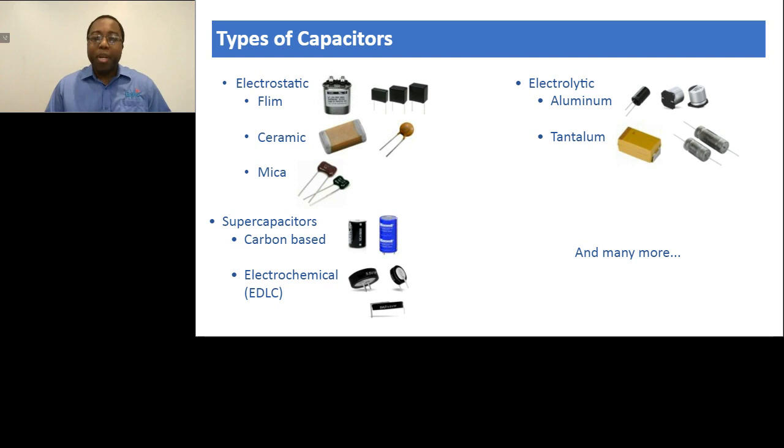The term supercapacitor is somewhat of a marketing term, but it is understood to mean carbon-based, or EDLC, electrochemical double-layer capacitors, and takes advantage of extremely high surface area to provide very high capacitance values, typically at lower voltages and frequencies. While these are the major families of capacitors, there are many others, especially when it comes to niche applications and technologies.